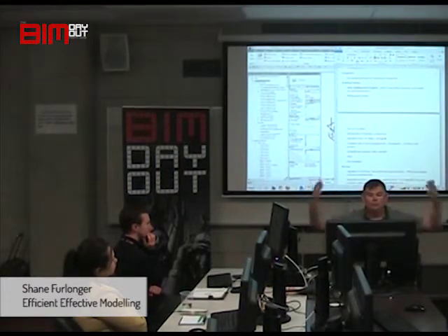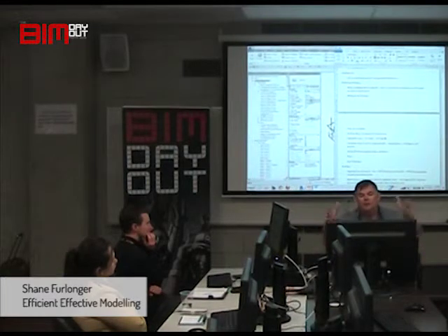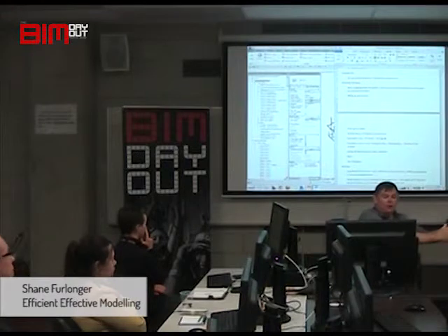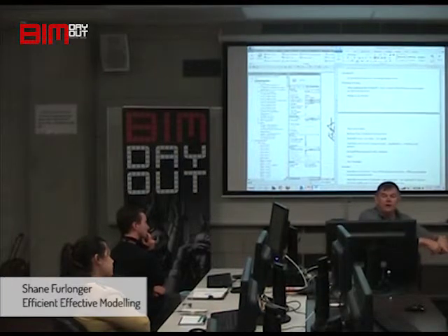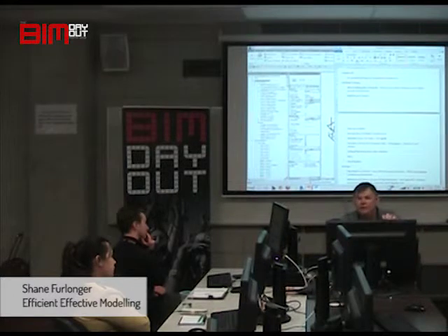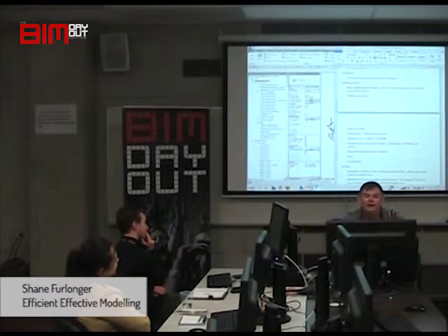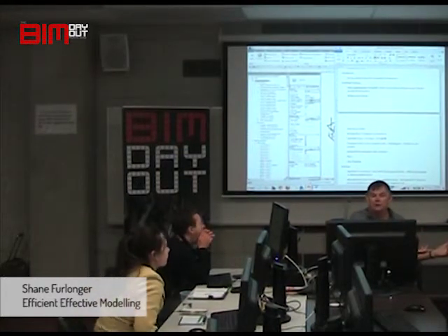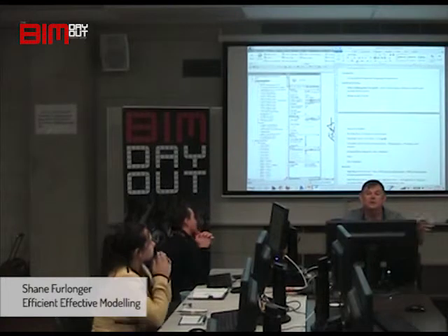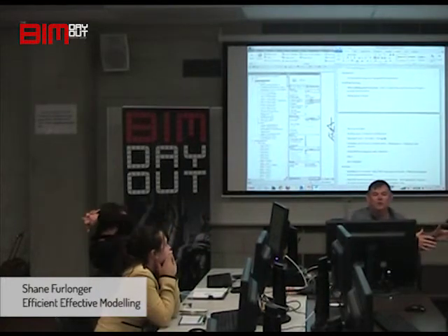So here's my window, and it's in legend phase, and I've got my working phase here, my new construction, and I need to increase the size of this window by 100 mils. I do it here. Because it's in a group, it does it here as well. But that particular item doesn't show up in my schedule of curtain walls because it's in a different phase, so it doesn't exist in the regular model.